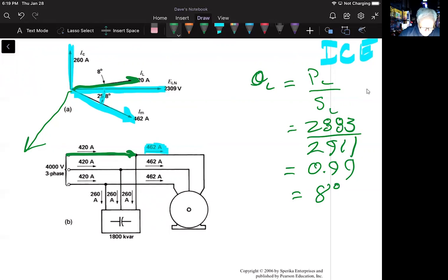The situation is somewhat different in the case of three-phase transmission lines. We can define resistance and reactance because the parameters are fixed. The same remark applies to equivalent circuits describing the behavior of individual machines, such as induction motors and synchronous machines. Okay, now that's getting way down the road. And like when we go into synchronous generators, for instance, we break this down and we actually do look inside of that and the reactances and resistances. But again, that's specific to a particular type of device. And what he's talking about is loads in general.